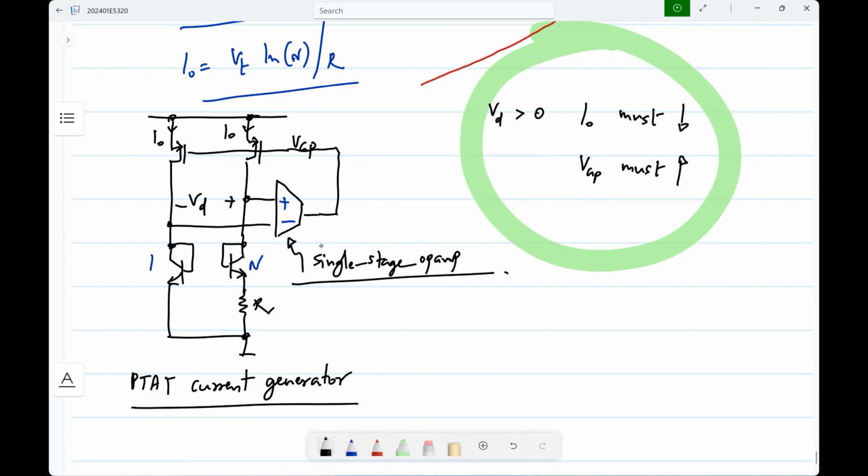You know that power of digital circuits is proportional to frequency. So if it is getting overheated, it is probably better to reduce the speed, consequently reducing the power dissipation, than let something bad happen to it. So they will have many temperature sensors all over the chip, and this could be one of them.